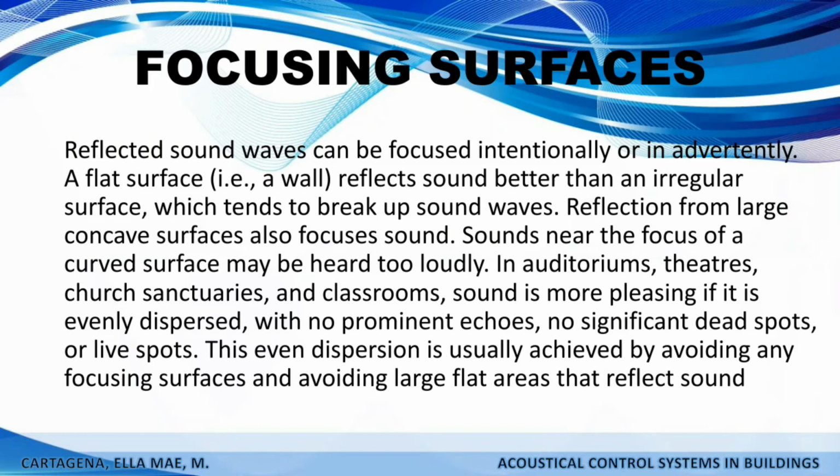Sounds near the focus of a curved surface may be heard too loudly in auditoriums, theaters, church sanctuaries, and classrooms. Sound is more pleasing if it is evenly dispersed, with no prominent echoes, no significant dead spots or live spots. This even dispersion is usually achieved by avoiding any focusing surfaces and avoiding large flat areas that reflect sound.